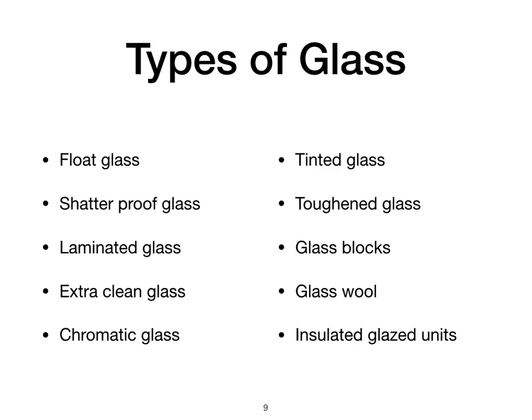Next is shatterproof glass. They are used for windows, skylights, floors, etc. Some type of plastic, polyvinyl butyral, is added in its making process, so it cannot form sharp edged pieces when it breaks.